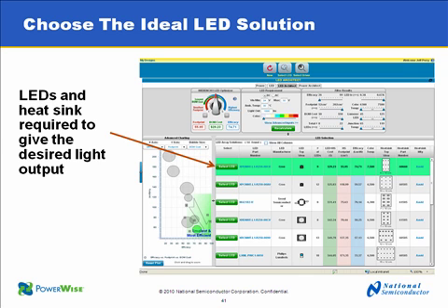Okay, so now we've hit the Recalculate button under that LED Requirements panel, and we see the list of candidate LEDs here. This lists the LED part number, LED manufacturer. It lists a top view image graphic of the heatsink and a heatsink part number. And so we're dealing with real stuff here and real pricing, because we have pricing on many of these items. It also gives you the cost of the heatsink and heatsink and LED, and it gives you a measure of the footprint of the heatsink in square centimeters and the efficacy of the system.